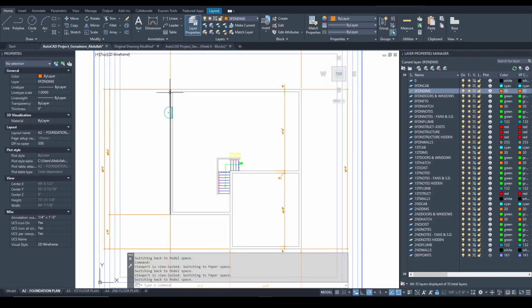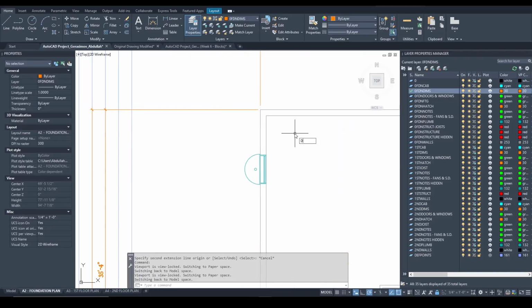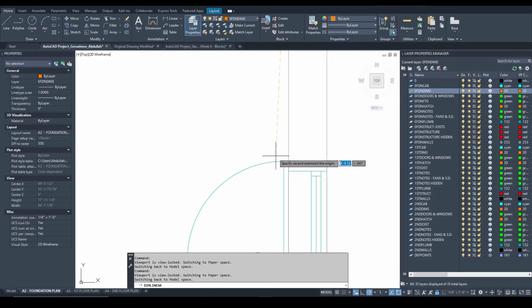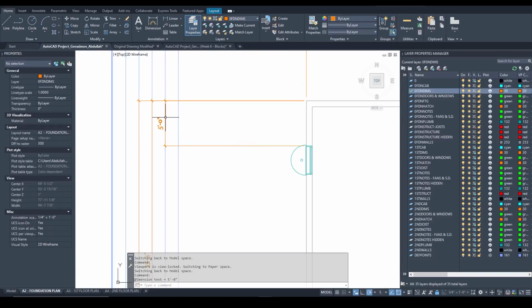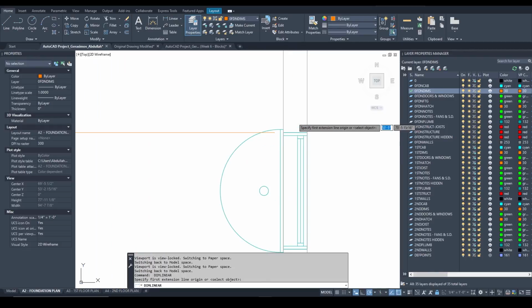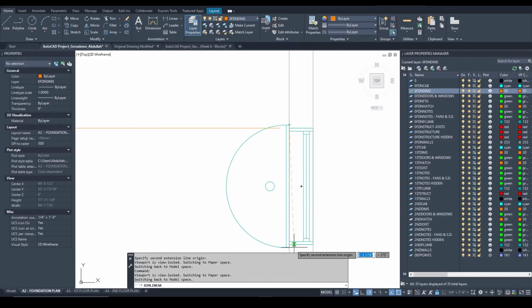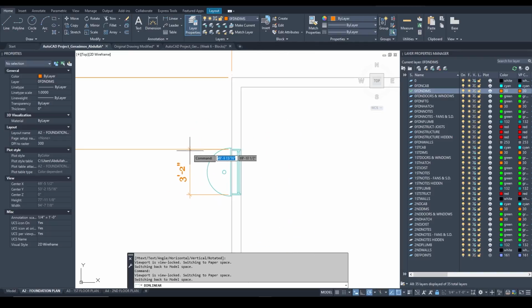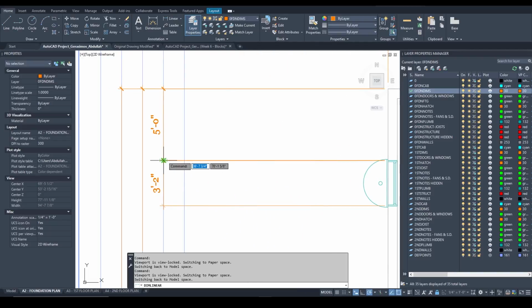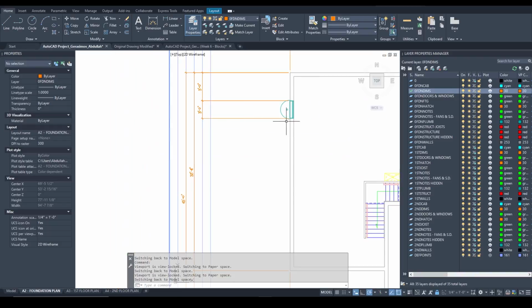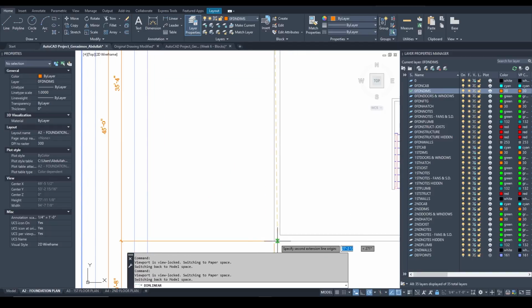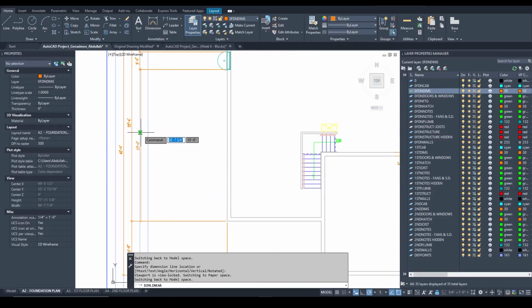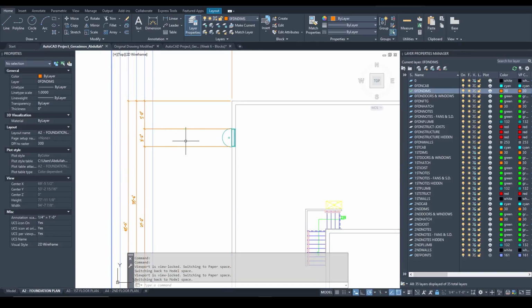Now that we highlighted where this wall is going and we made sure it aligns with our PDF, let's also highlight where this window well goes. Let's start from this corner and end over here at the edge of the wall. Go to this location. I press spacebar because I like making things easy for myself. And our window will be 3'2", and one more spacebar, this corner and this corner. And now we have located our window well.